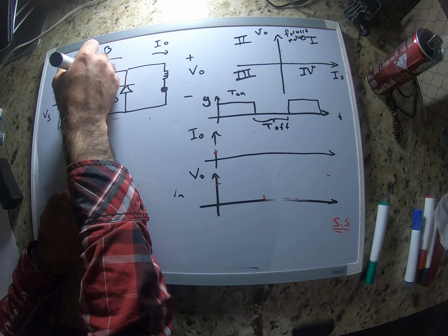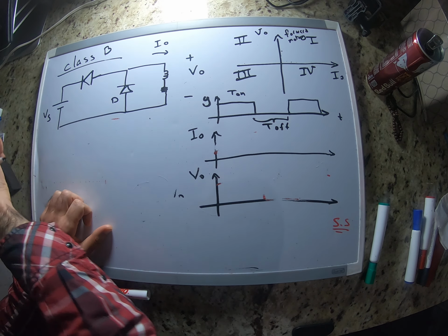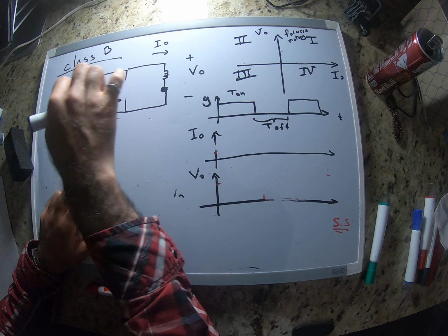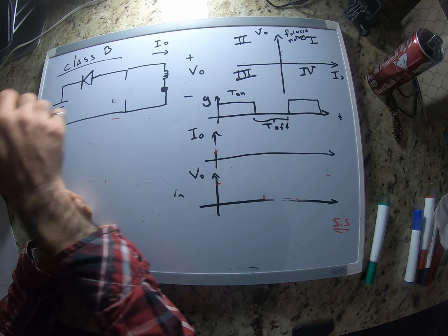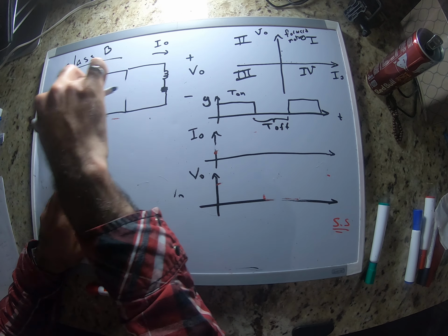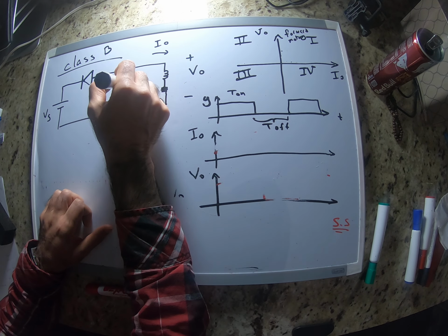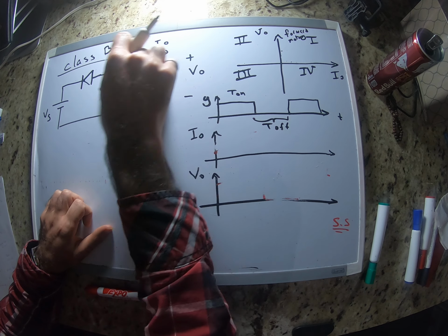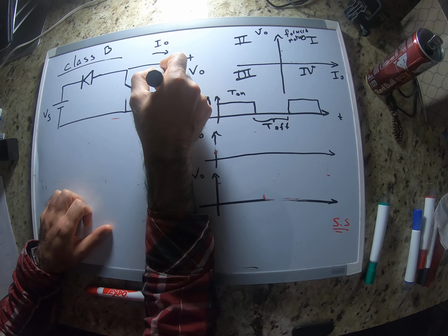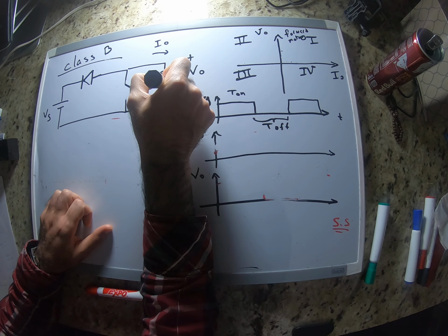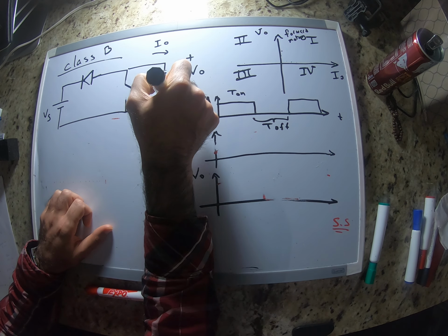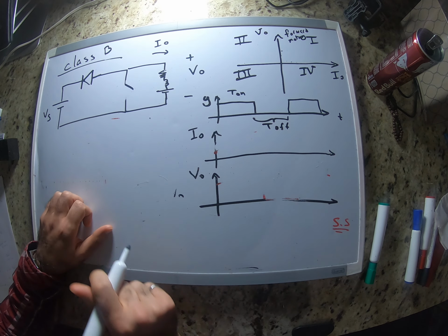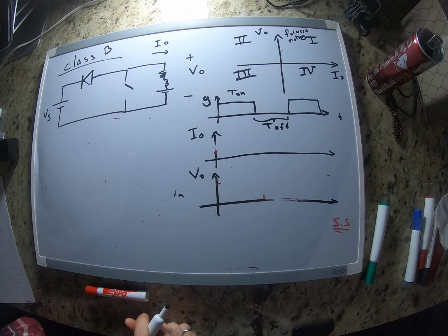We have a diode in this direction, and we have a switch here, and we have an RL circuit. Let's just make this the model for a motor. So we have an RLE, right? This is how we can represent a DC motor. Okay.